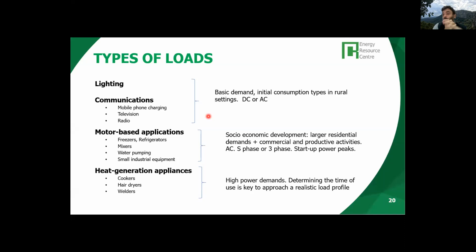When we think of motor-based applications, obviously in AC, we can think of single-phase systems versus three-phase systems. If we need to cover a large area with a low voltage distribution mini grid in a village, for instance, we might have advantages designing it in 3-phase rather than single phase.